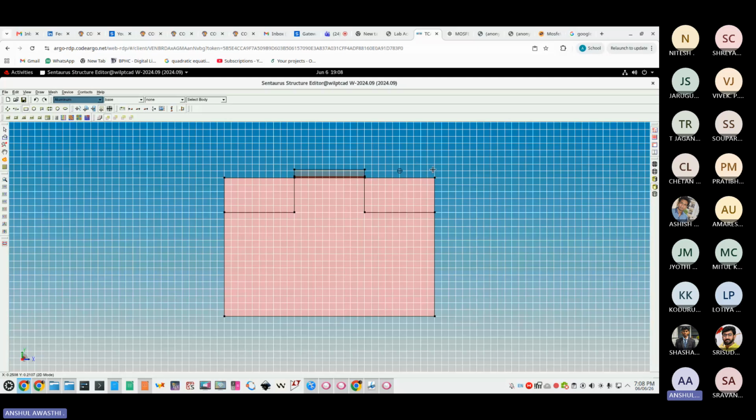You can create them: it will go from 275 to 300 in x direction, and in y direction from 200 to 202. Similarly here it will go from 0 to 50 in x, and in y from 200 to 202. In this way, those seven coordinates you can define. Here I am not defining them, I have just applied the contact directly.